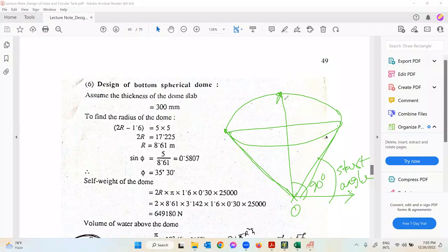And how about the latitude and altitude? So you just go like this. These are the altitude, right? So how many of them do you want in your model? As I said, if you want 10, then there will be 10 slices. Okay, if you want 20, then there will be 20 horizontal slices. So there will be one top dome, and there will be 19 more slices like rings.